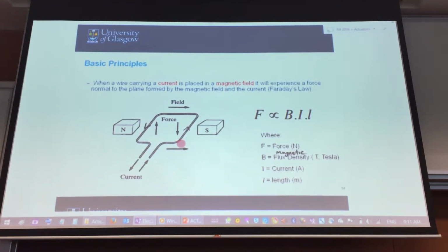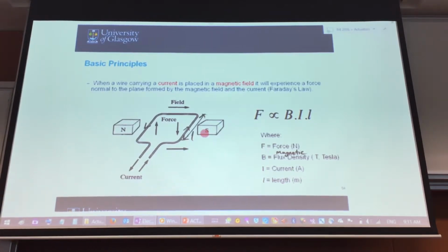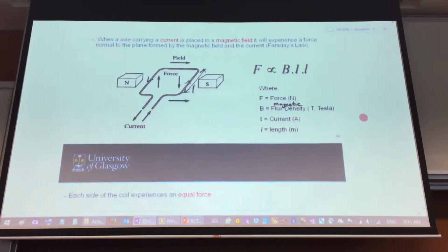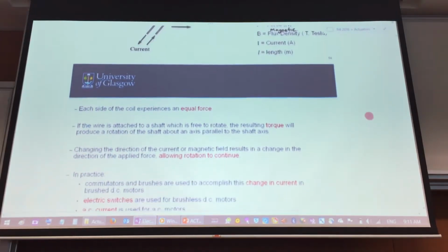And if you want more force, then you extend the length of your wire. So the length will be provided by that. That will be L. The longer that length, but that length has got to cross over the surface area of your magnet, so they have to match. So if you have a long length and long magnets, providing the north and the south pole, those are the things that will govern the amount of force that you can obtain.